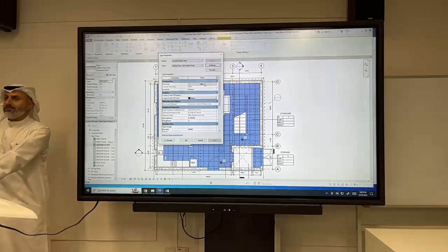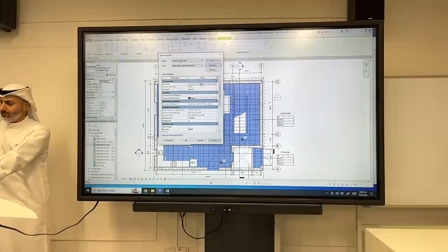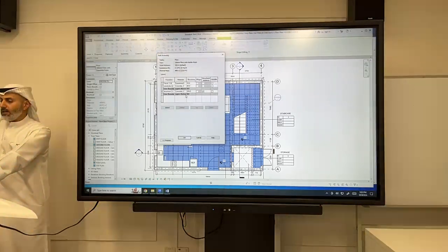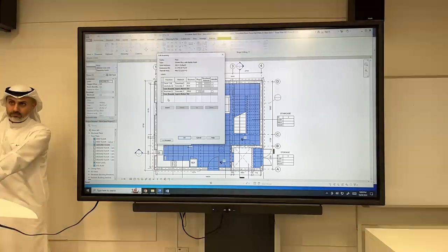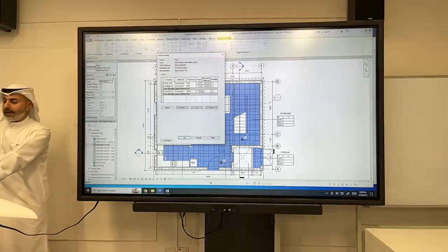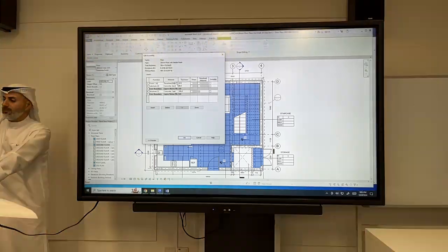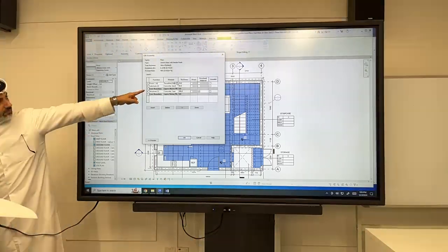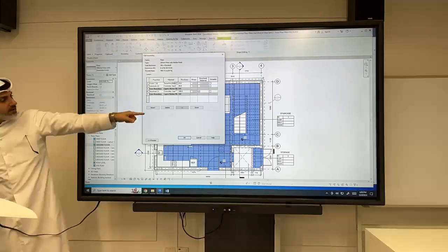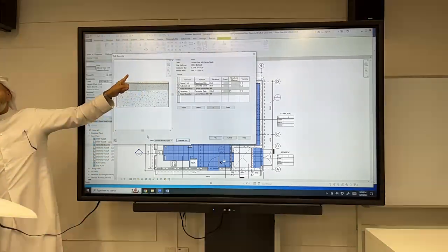What did you change? From where? Structure, edit, structure. Then change the finish at the top. Exactly. So the finish is the first one, number 1. You'll see travertine 500 500. Click on those 3 dots in here. It's number 1, finish. The top layer, that's what we want to change. If you look at the preview, this top layer is what changes it.